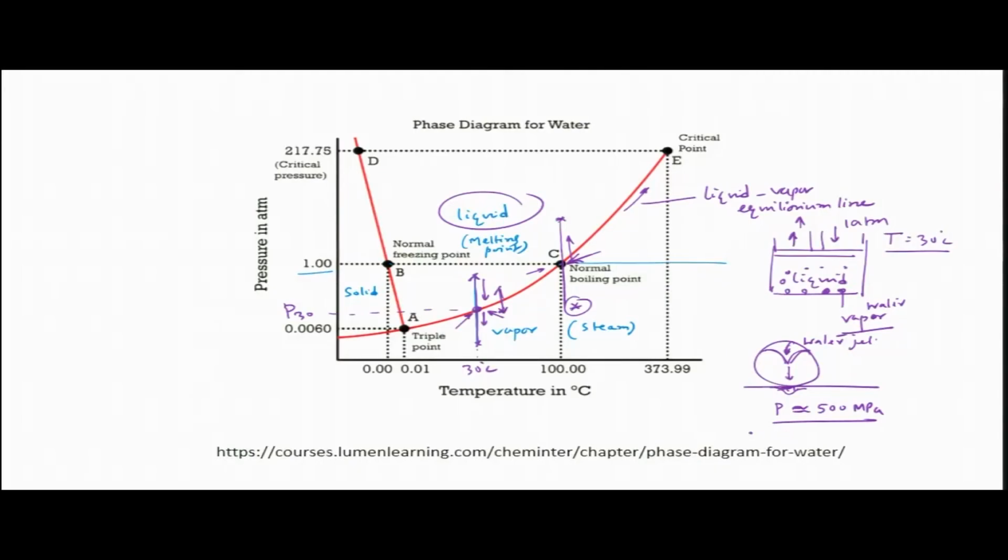So, that means if this much pressure is exerted, it will yield, because this particular stress is more than the yield stress of the mild steel. So, then it will definitely yield. So, there will be deformation. Okay. So, the material would get like this. So, the small deformation would start. Now, we know that the deformed part is very active. Very active. So, if it becomes very active, that means the corrosion would start, a higher degree of corrosion would start.